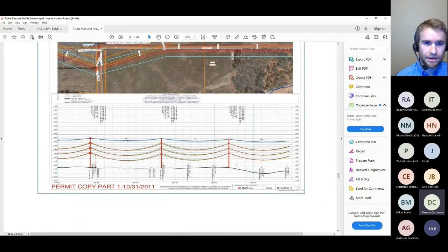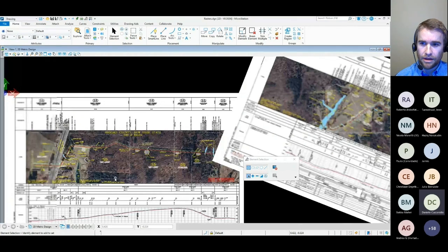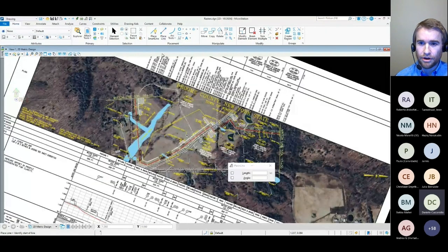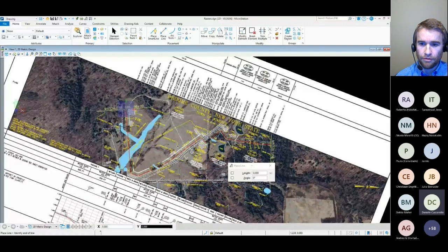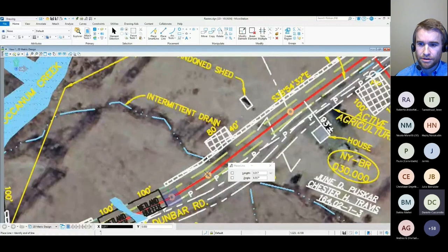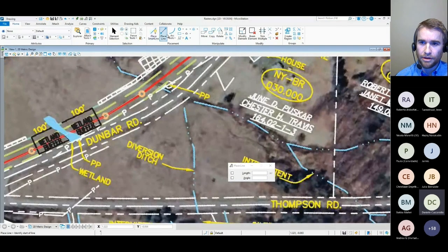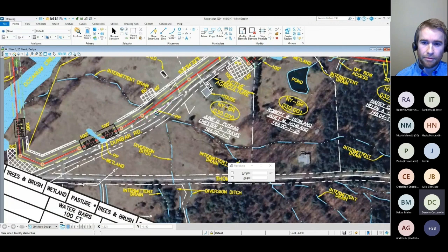So taking this information, we can use another type of CAD tool. So here I have MicroStation, for instance, where you can just take those plan profiles, place them into the drawing, and then after scaling, we can start drafting over a rough path to illustrate where our pipeline is. And we do a similar type of operation in following the pipeline path. So we would essentially follow the lines that are illustrated there to create our path for both our pipeline and our power line.